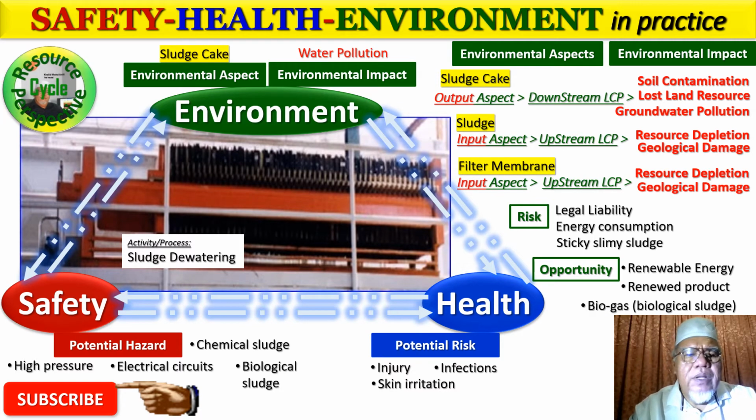Nonetheless, some of these sludges, due to excess application of polymer coagulant in the coagulation tank, would result in most of this sludge being sticky due to the slimy character of those flocculants, especially polyelectrolytes. Okay, that is another issue.